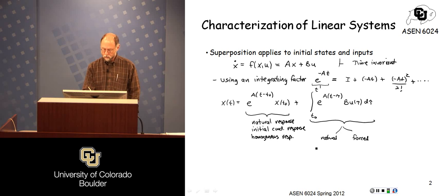This is often called the zero initial condition response, because the initial conditions are zero. We don't have this term over here at all. We just have this term. You can also think of this as the input-output response.